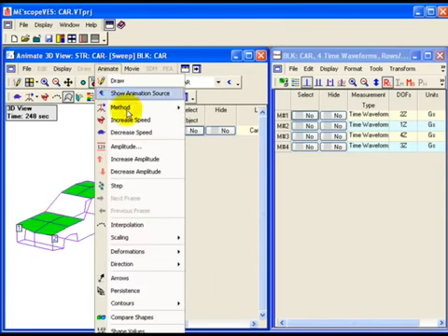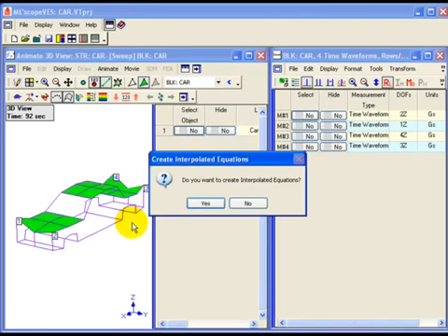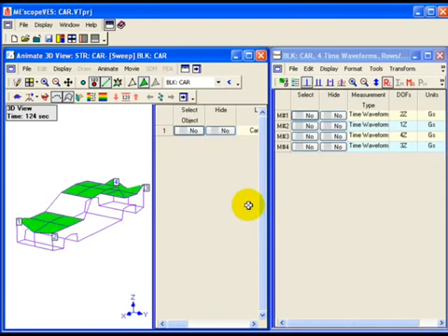Execute Animate, Interpolation to enable interpolation. Press the No button so that no interpolation equations are created. The structure model will again be animated with shape data generated by sweeping the line cursor through the data block traces. But without interpolation equations for all of the unmeasured points and directions, only the 4 measured corner points will animate.